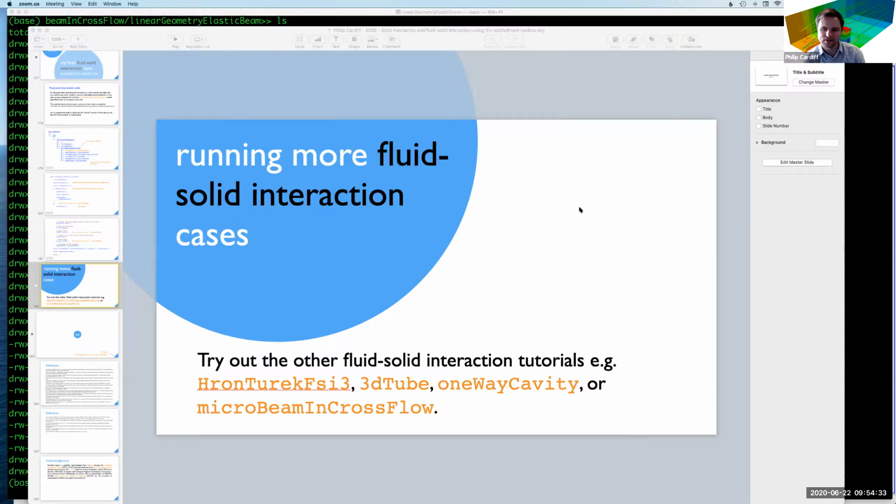That's one difference between finite element and finite volume. If you move the mesh in an updated Lagrangian method, in finite element you have the displacements at the vertices, whereas in finite volume you have to interpolate them. So you have to be careful how you do that, as you can introduce some errors. Though generally, I haven't noticed that they've messed with the solution in any major way. But yeah, interesting question.